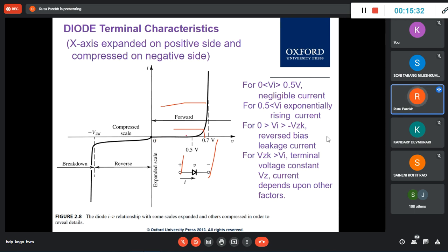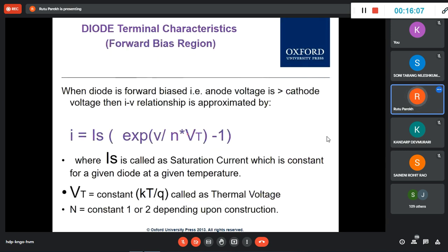That way, the resistor also has a characteristic. If instead of a diode you have an R, and I'm just showing you R separately, then the line will be linear, depending on R. For one voltage, only some current. For another value of R, it can be this way. So this is R1, this is R2, let's say. For this voltage through R1, only this current will pass, and for this voltage through R2, only this current will pass. So this is also fixed for R.